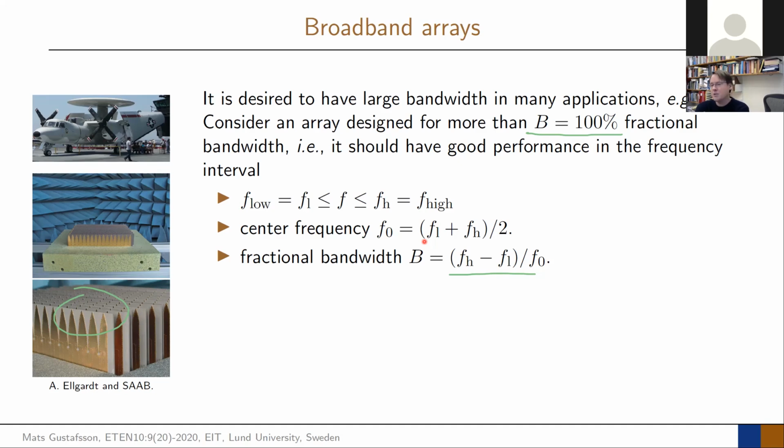But of course, it's coming also in a communication setting, because imagine now the base station scenario. You put huge arrays there. And if you have large arrays, you should cover, of course, all the frequency bands. And you cannot make one antenna array for 700 megahertz, another one for 900 megahertz, and then 1800, 1900, 2.35. Maybe you could cover all of those in the same array. Then you would like to have actually one array element that deals with them all in some ways, which can be a huge advantage in many cases. But when we do that, we really have to ask, how do we design it and what comes in?